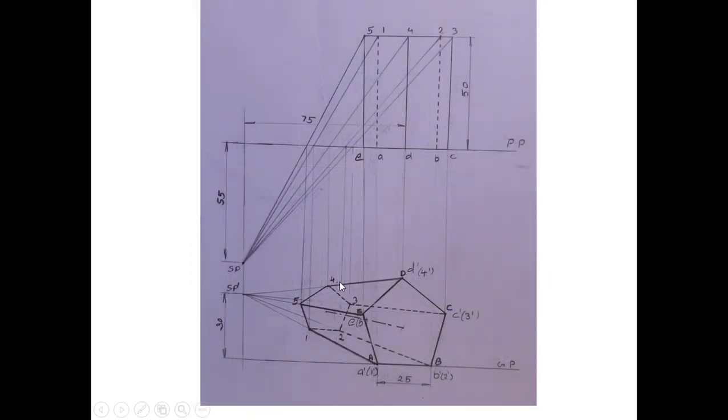Also, now in this case, since the object is observed from the left side, you can easily identify that points 2 and 3 will be invisible, because now 4 will be at the top, 1 will be lying on the ground, and 5 is already visible on the side. So the points 2 and 3 will be invisible. So in perspective projection, all the lines to the points 2 and 3 will be invisible. You can mark those lines 4-3, 3-2, 1-2, then 3C and 2B as invisible. So those lines you can mark as dotted lines.